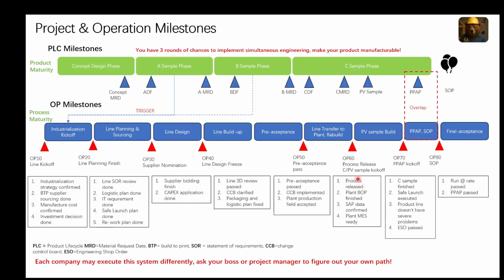It's different from PV. PV is the whole product level. Sometimes some critical processes you need to check one by one. For example, for soldering or laser welding, you need to make sure that the pulling force of the copper is okay.